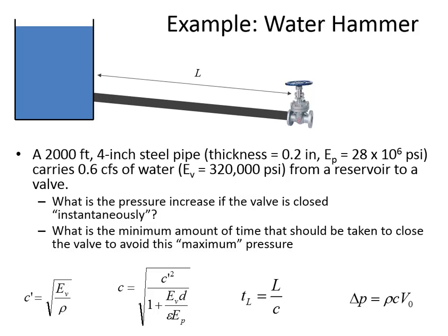320,000 pounds per inch squared times 144 inches squared per foot squared. And then we multiply that by the diameter, which is 4/12 of a foot. And the thickness of the pipe, 0.01667 feet, is how thick this pipe is, because we know the thickness is 0.2 inches. I've converted that into feet to get the thickness of the pipe.